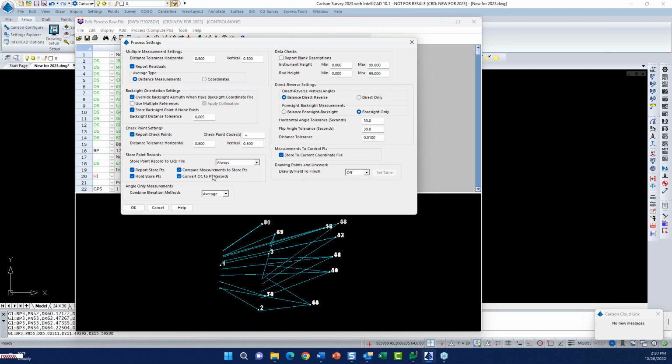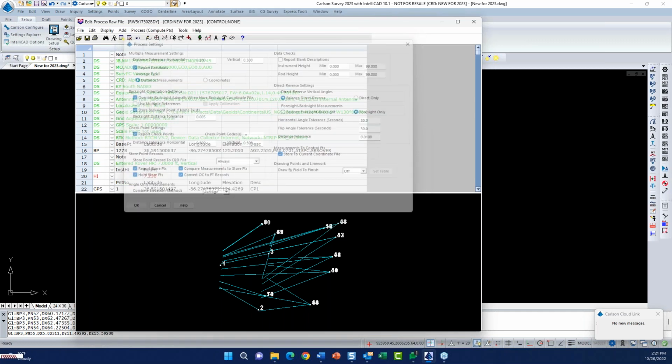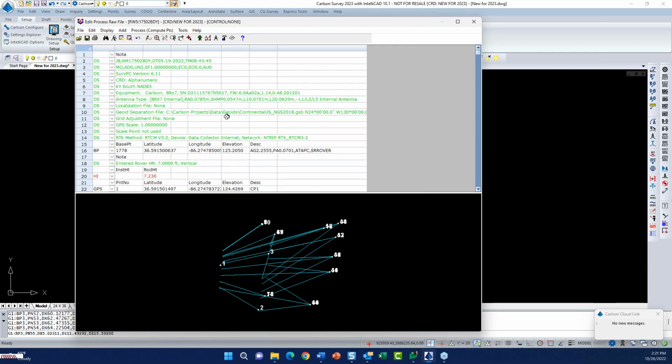So all that information gets added to your report when you process your raw data. So those three upgrades I consider pretty significant, because in prior releases you'd have to do a little bit more work to get those comparisons. You've always been able to do it with checkpoints, but now it actually finds a PT record and logs any differences that you got.